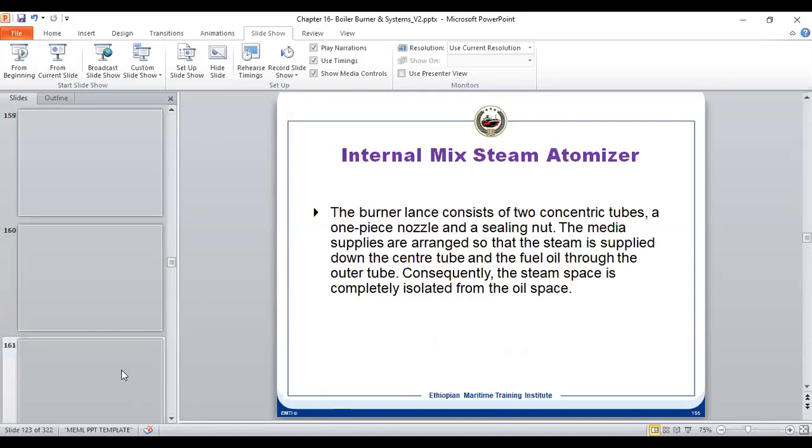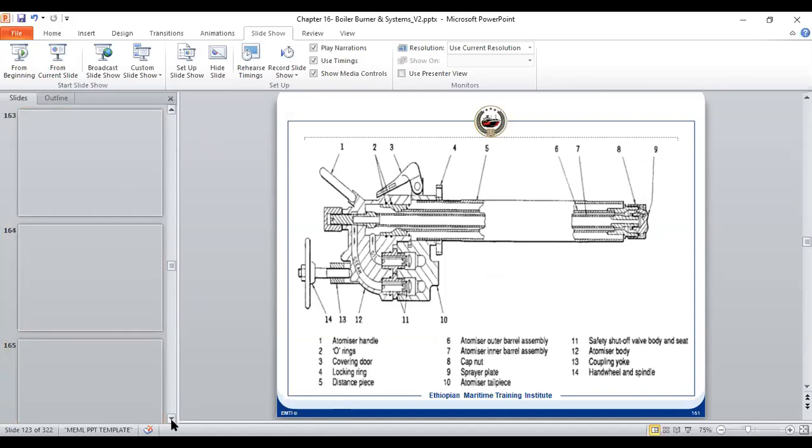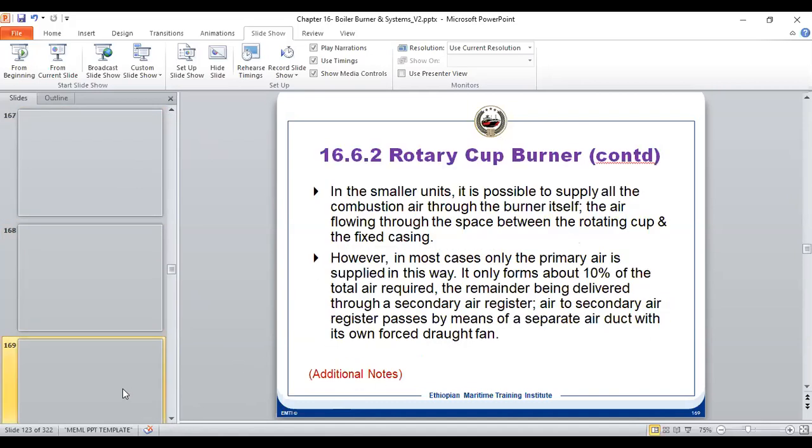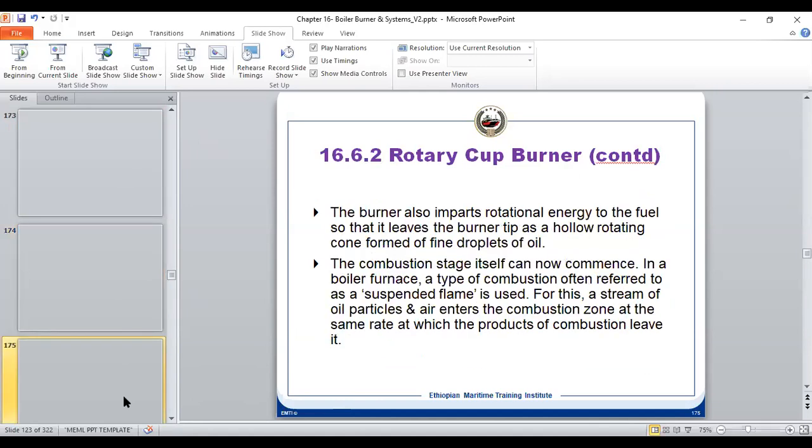And boiler survey does not depend on the age of the ship. It is 3 years fixed, whether it is for main boiler or propulsion boiler, or auxiliary boiler.